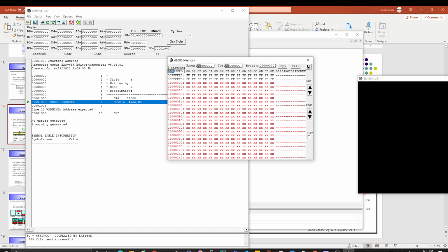Normally when you play with the memory, you put the data from left to right, but in the case of the stack, you save the value from right to left, going down. If you save a value to the memory, it goes from the small values and increases to the higher memory locations, whereas for the stack, the address decreases, going down.